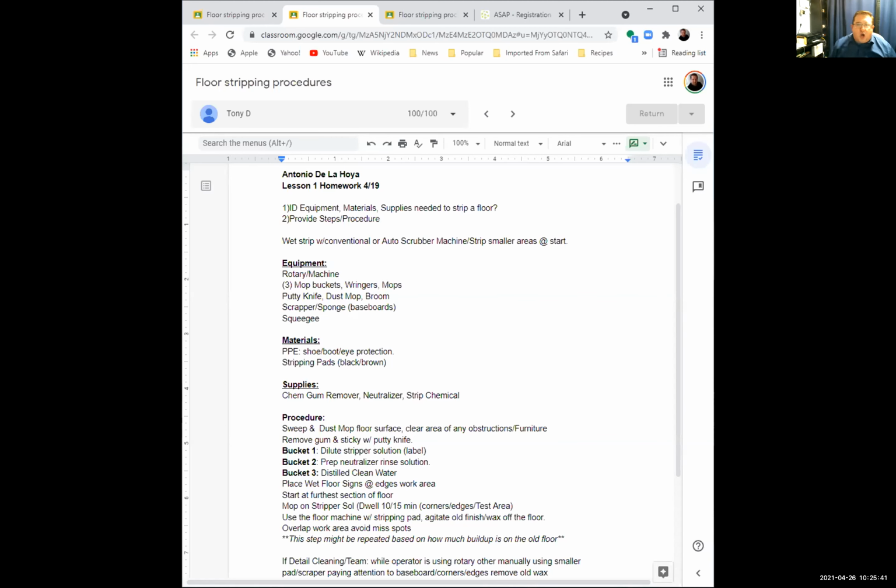One of the things I will caution against, until you get to the point where you're very comfortable laying finish and you've been laying finish for quite a while, is trying to go way out with the swing of your mop. I've seen guys who are really skilled at this. They never miss anything, and they can cover a large swath, but they're laying finish 5 days a week, year round. Those guys are great at it.